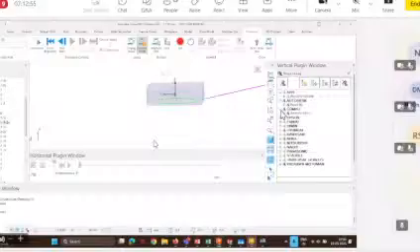Then the next step is to go to the robotic cell. Here we need to define the position of the part in the actual cell. You click over here, and if you go to robot convention, then you can specify where your part is as per your robot world coordinate system. The robot world coordinate system is defined for the given robot.